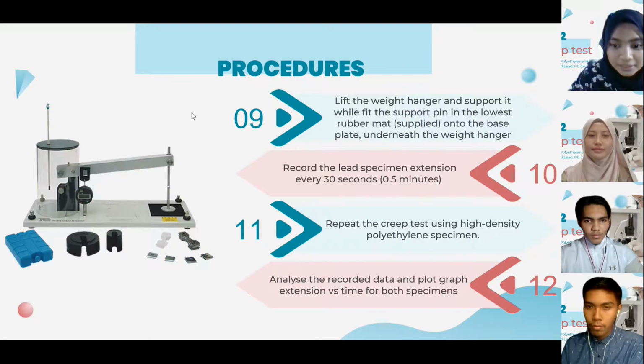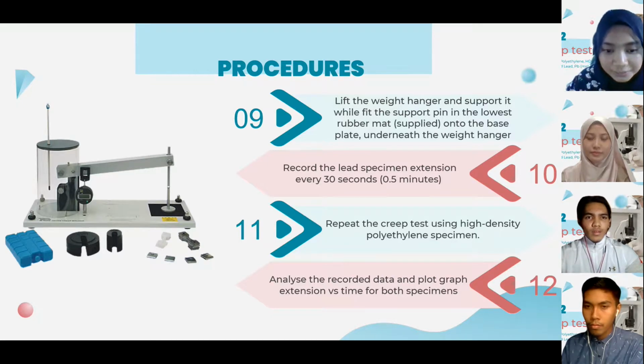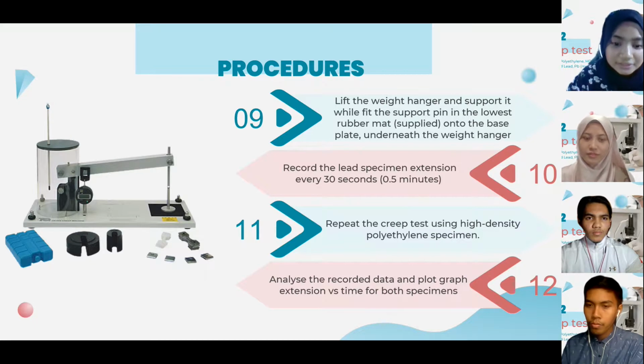Then we lift the weight hanger and support it while fitting the support pin in its lowest hole, with a rubber mat onto the base plate underneath the weight hanger, and record the lead specimen extension every 30 seconds until it fractures or stops extending due to the limits of the machine. Then we repeat the creep test using the high-density polyethylene specimen, and lastly, we analyze the recorded data and plot the graph of extension versus time for both specimens.